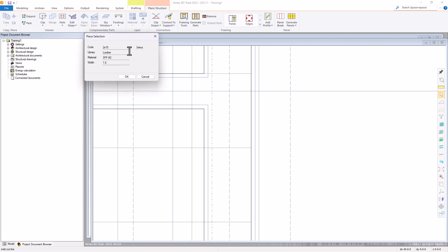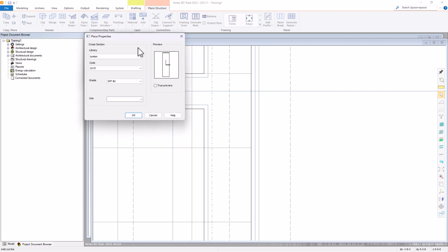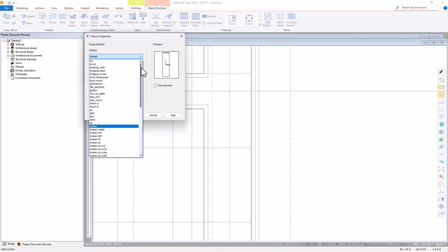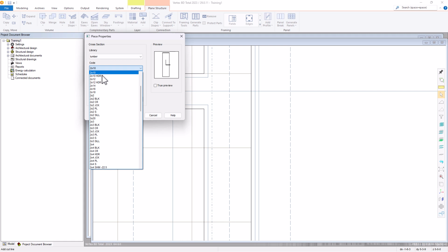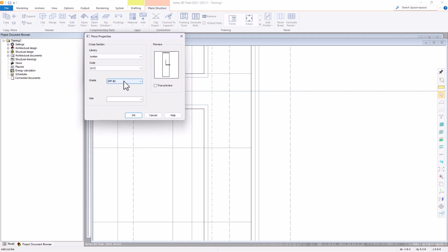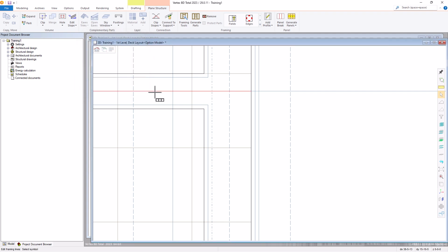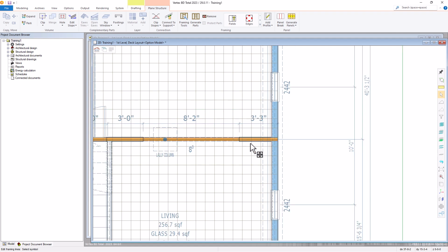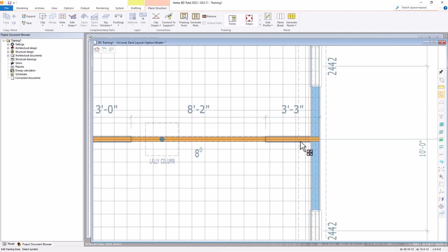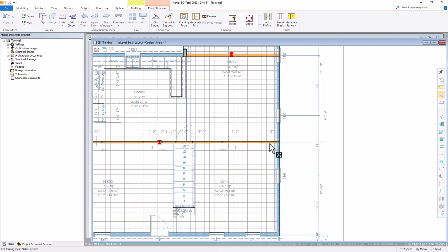And we'll go to Parameters, Wood Select. Let's just go ahead and add 2 pieces of 2x12. Yeah, we'll just leave it at lumber. Select 2x12. I'll just change it to number 1. Hit OK. And select OK and OK to close this window. And now when we zoom out, you'll see that we have 2 members. And again, a framing line associated with that beam.